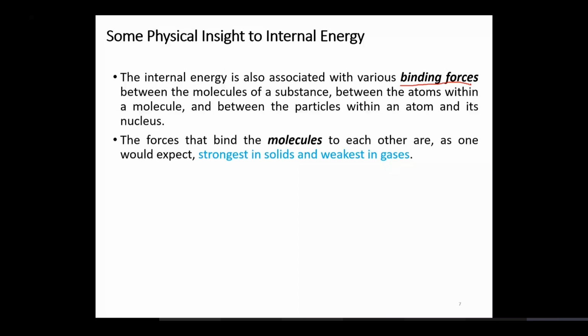So the energy which is related to the phase change of the system, that means the energy required to overcome the binding energy of the molecules in order to convert it into another phase. That is the phase change part or phase change energy of the internal energy. So internal energy once had the sensible part, which is related to the kinetic energy of the molecules. The other part is basically associated with the phase change of the system. Clear enough? Is this part clear?